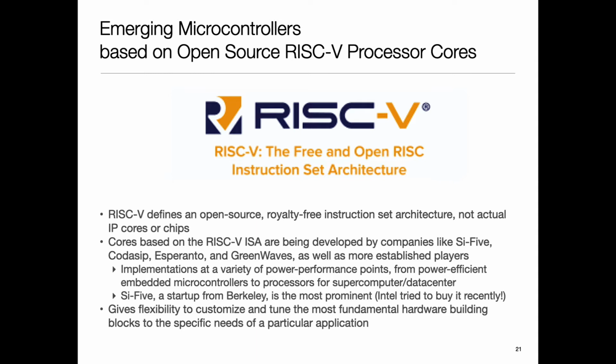what Berkeley did is define the instruction set architecture. If you've done a computer architecture course, they always talk about the instruction set architecture, essentially the set of assembly instructions, and there is the implementation. I can take the same ISA and have many different implementations of it. Some implementations may have different cache sizes, maybe different levels of pipelining. They may differ at the microarchitecture level, but they all execute the same program in the same instruction set architecture.